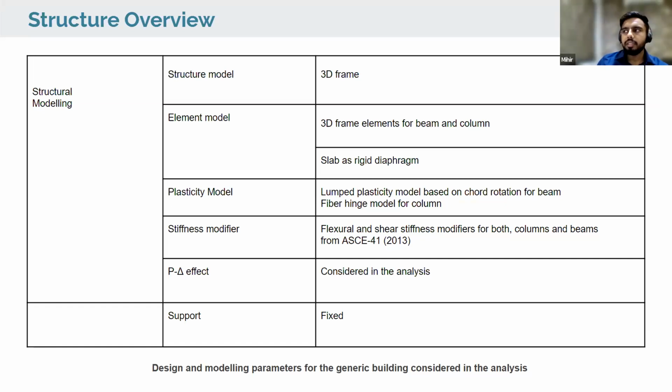If I talk about the industrial approach, generally the frame elements are majorly used, but when we need to deal with finer, more accurate results, where we are talking about some steel connections where you want to see how the stresses are behaving, at those locations we use the plate elements. While for research purposes, we go in depth with the analysis and results, because the behavior of the structure is quite important to understand. That is why you use those higher end elements for research.